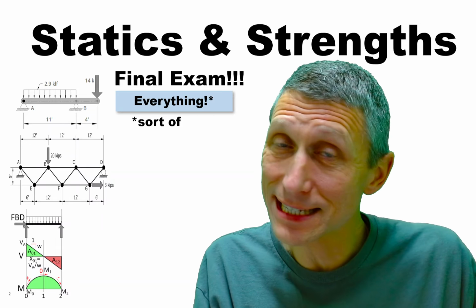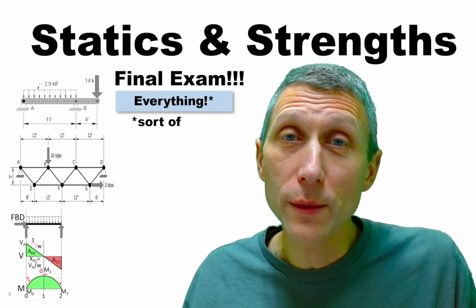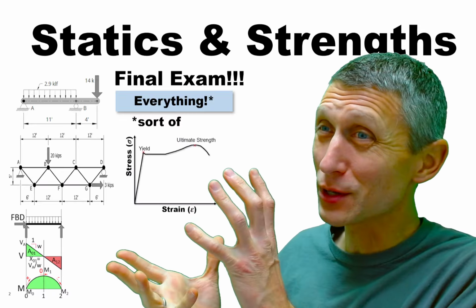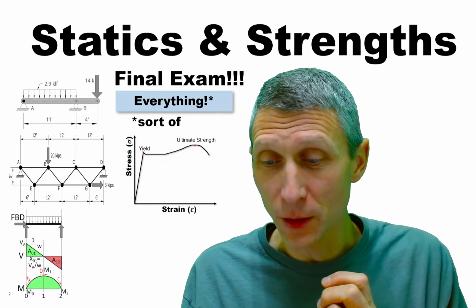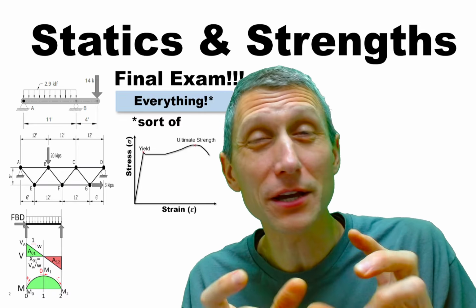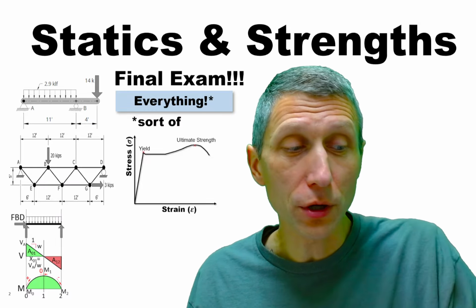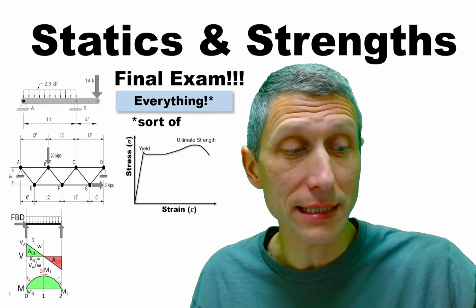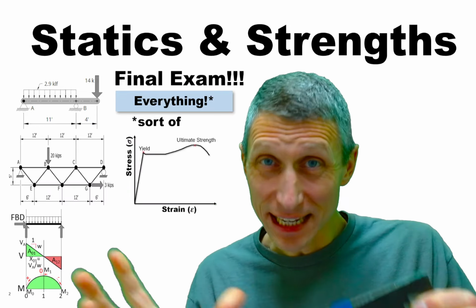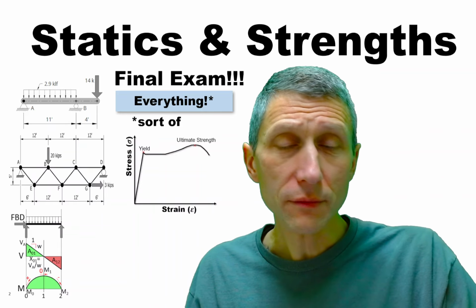Now it doesn't stop there, because this course combines statics and strength of materials. And when we get to strength, one of the things we started to do was look at something like a stress-strain or force-elongation curve. These curves are important because they help us understand material behavior. What's happening when we start to pull on a piece of steel? It's going to stretch up to a certain point, and then it's going to yield and permanently deform, and then it's going to strain harden, and then eventually it'll rupture.